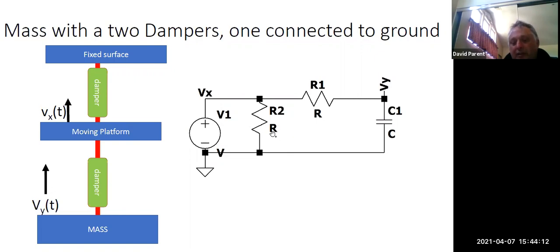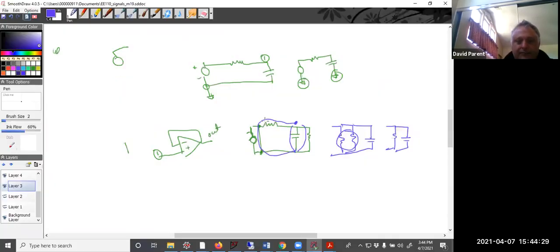So this was kind of like a 98 problem of, what's the time constant of this circuit? And in this case, this resistance doesn't come into it. And there's two ways to look at that. If I put a step here, if this is an ideal voltage source, it can supply all the current it needs through that resistor, and still this node will go to that step voltage. And so in fact, you just have the traditional 1 over RC.